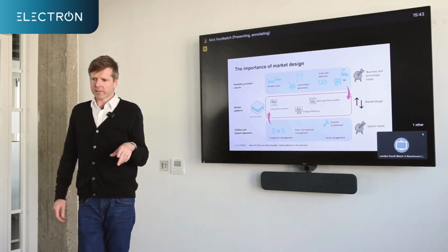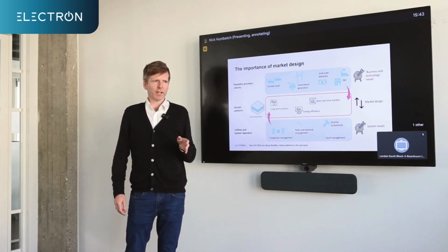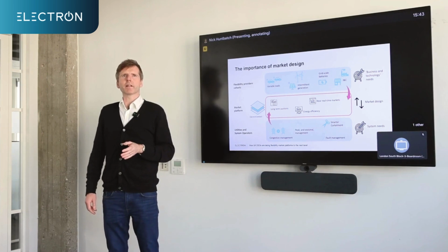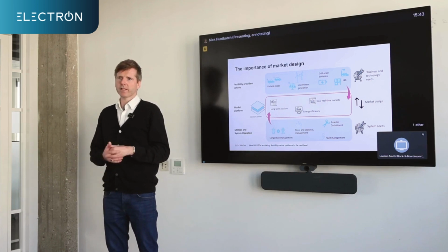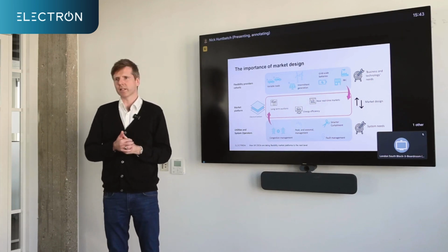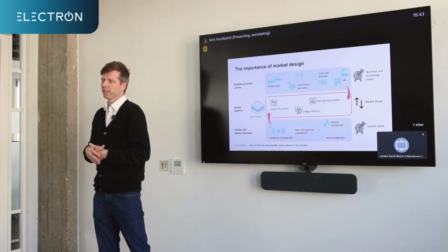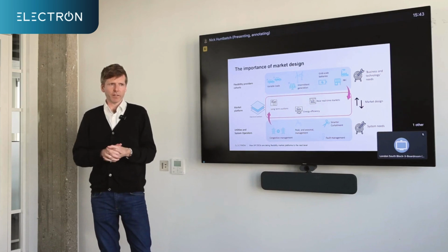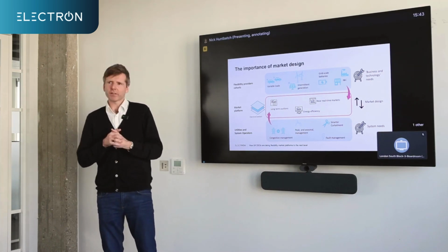And then an interesting use case. When we talked about curtailment before, as in the system is going to cut people off because the network's under constraint, if that's not being done in the best way, it causes the network operator a problem because they need to be using that clean energy. They need to be curtailing people in a smarter way than just doing last in, first out. So smarter curtailment is definitely a need for a system operator.